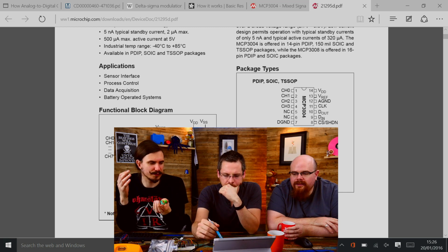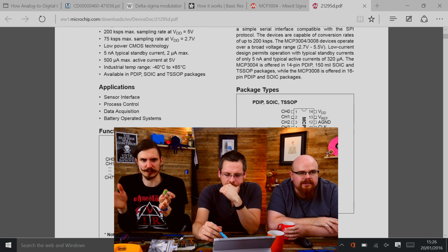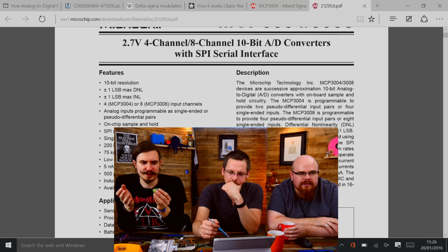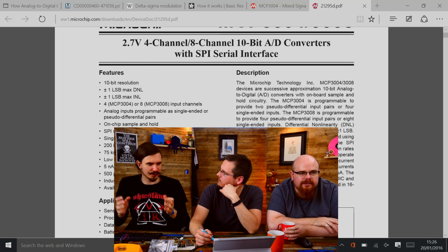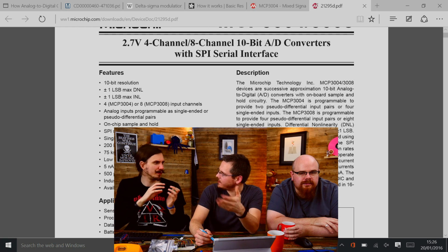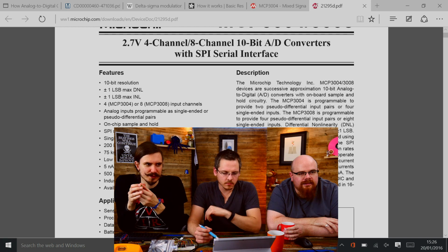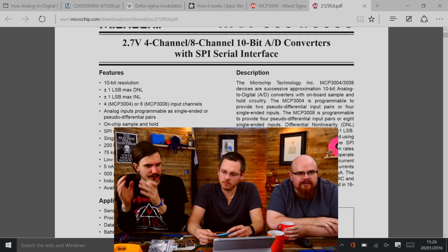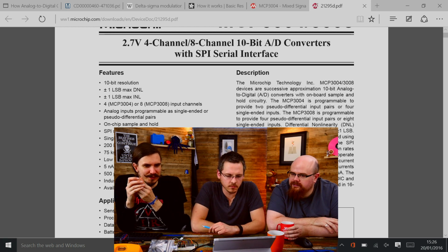And then when the ADC has completed its conversion, which obviously takes a period of time depending on how fast you're driving it, what frequency you're running it at, it will notify the PIC, and the PIC will go, aha, value now, and then it can stop what it's doing, grab that value, quickly slurp it in, and then carry on and leave the ADC to continue its thing. So you don't have to be overly attentive with ADCs. You don't have to constantly be going, you got the value yet, you got the value yet, because it's painful if you do it that way.